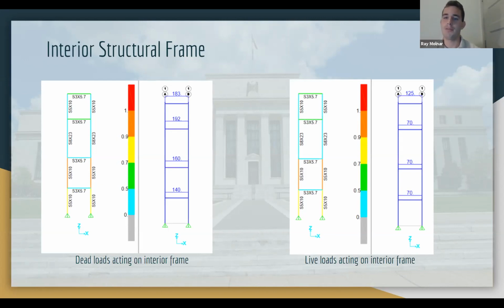And so the sweet spot for each beam and each column is around that 0.9 area on the scale, because this was where the cost of materials can be minimized while still maintaining the system's structural integrity. So if your DC ratio is far below 1, in other words, if the colors are very close to the bottom, then it's obviously overbuilt, where it's over designed, where money is being wasted on heavier duty material when unnecessary.